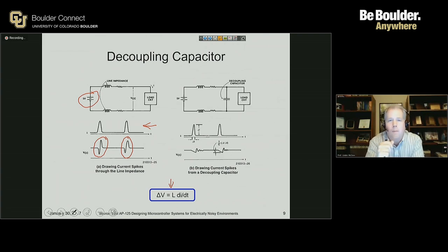Yes, in the front. Some devices that have a VCC requirement will shut down if they're not getting enough power. But another piece of that is, if your voltage delivery is not staying within the specifications of your integrated circuits, then your integrated circuit is not going to perform the way the datasheet says it's going to. And how it does not perform according to the datasheet, you may not be able to anticipate. It may still work but have varying characteristics, or it just may not function properly at all.